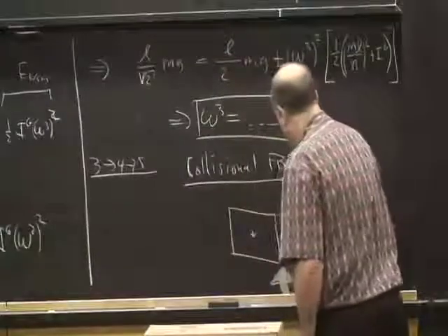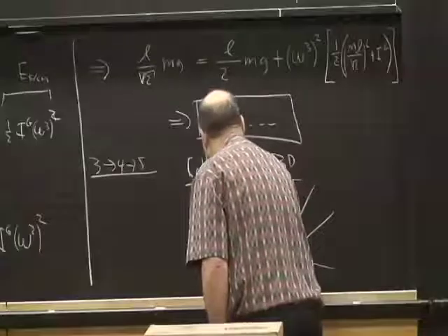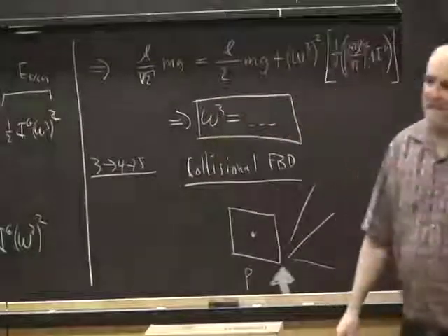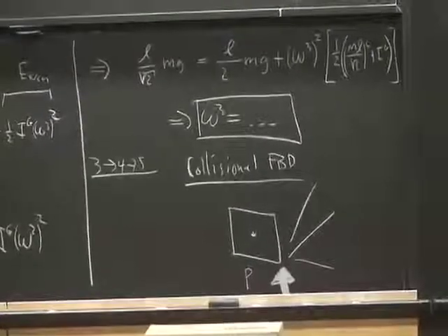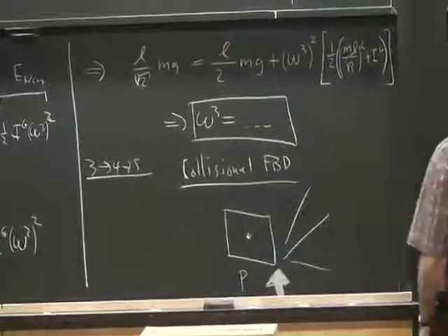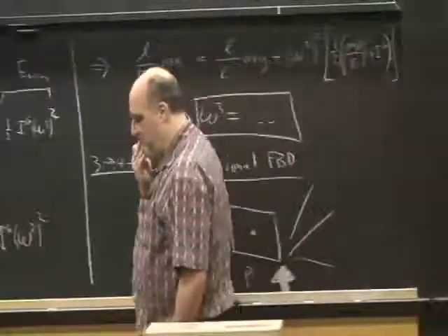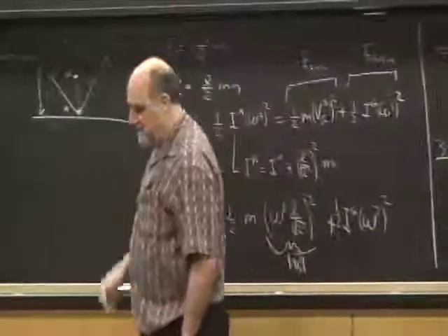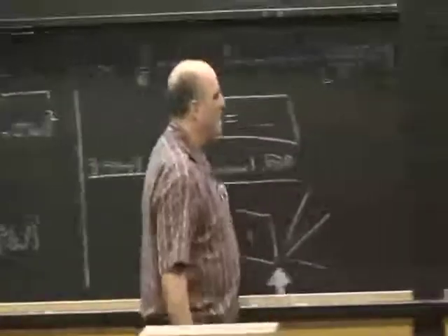So this big force, bang. I'll call this P, or I can think of it as a big force, or I can think of it as an impulse. And for this purpose now, I'm going to think of it as an impulse. So what we'd like to do is take angular momentum balance, and there's two ways we can do this. We can jump to the impulse equations, or we can derive the impulse equation from the angular momentum balance equation.